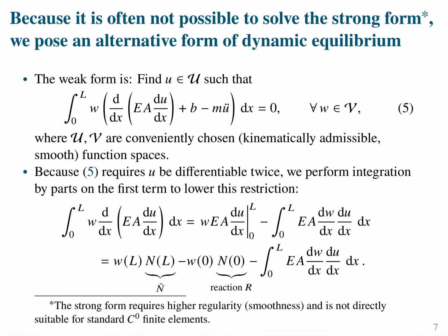Why do I want to work a little bit on that expression? Well, if you notice, we have a second differentiability requirement on our function U, right? Whereas the weight function doesn't have any differentiability requirement. So we're going to do integration by parts. This is the result of integration by parts already. And you see that when I apply integration by parts only to this term, because this is the one that has the second differentiability requirement, we are able to balance the derivative. So now I have a single derivative on u, I have another single derivative on w, right? So I'm balancing the derivatives. This is actually great for many reasons that I will share in a minute.